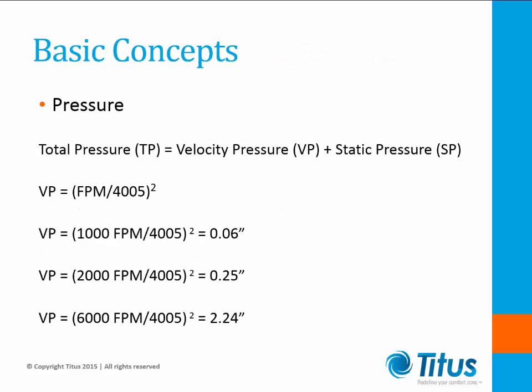Let's get started with our basic concepts. The first basic concept we'll discuss is pressure. Pressure is the heart of duct design. We'll be discussing total, static, and velocity pressure throughout the webinar today. Total pressure is the sum of velocity pressure and static pressure inside the ductwork.